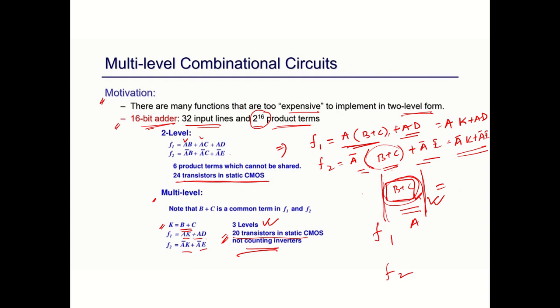What we have for two label are different Boolean functions. These Boolean functions will be represented with the help of different AND gates and OR gates. Based on these AND gates and OR gates, obviously the number of transistors is defined. So if we reduce one AND gate, this can reduce 4 transistors.